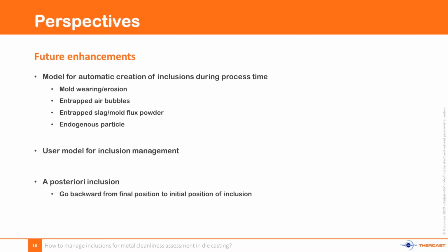So depending on the case, in particular in HPDC, where air bubbles have quite a big impact on the inclusions, it is quite interesting to have a possibility to automatically create the air bubbles. The same for the slag, mold flux powder, mainly for continuous caster and ingot casting process.